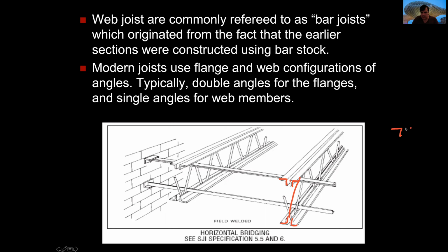They are quite tall in section, and the width is relatively short. Therefore, they will tend to move and rotate in these directions depending on the loads. In order to eliminate that possibility, you can have a connection with the next joist and have more stability.